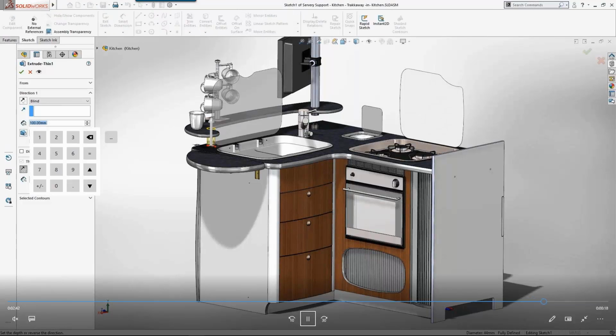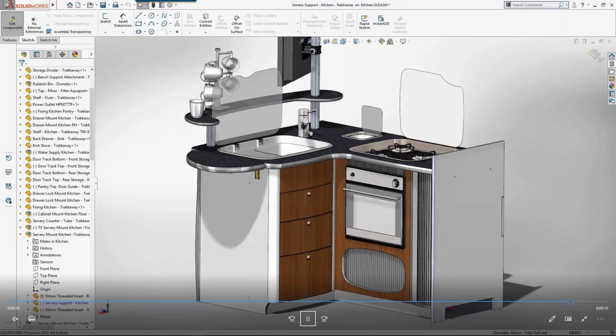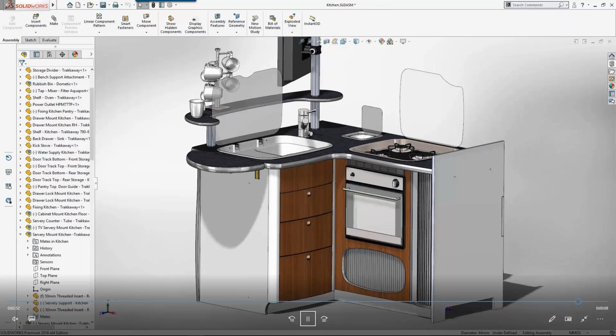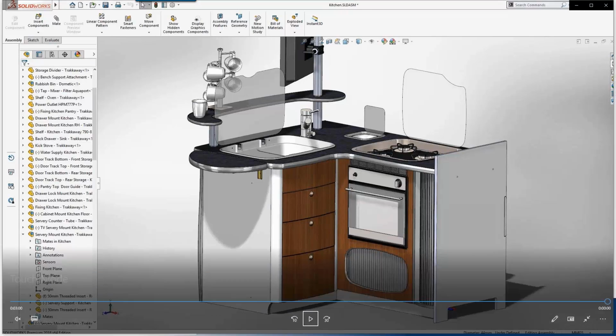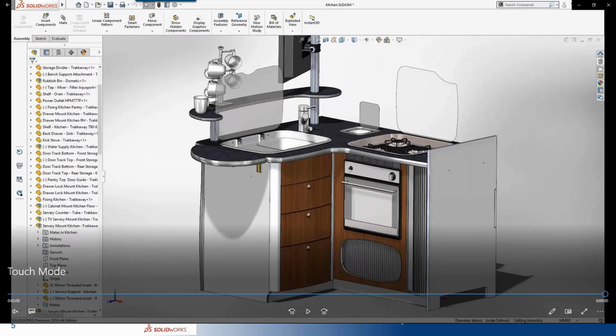The new Touch Magnifier tool is a great way of enlarging a small area by making a selection while keeping the rest of your design in view. Just press your finger on the screen for longer than 2 seconds and then drag the magnifier into position. At the same time, dynamically adjust the zoom level using the touch toolbar controls with your fingertips, and with your fingers released, object crosshairs stay selected easily.